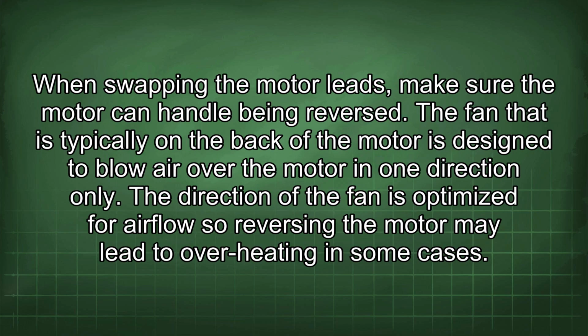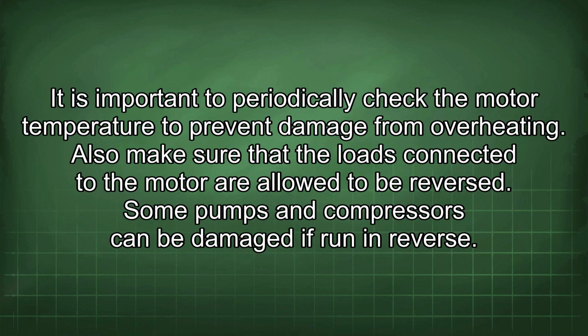When swapping the motor leads, make sure the motor can handle being reversed. The fan that is typically on the back of the motor is designed to blow air over the motor in one direction only. The direction of the fan is optimized for airflow, so reversing the motor may lead to overheating in some cases. It is important to periodically check the motor temperature to prevent damage from overheating.